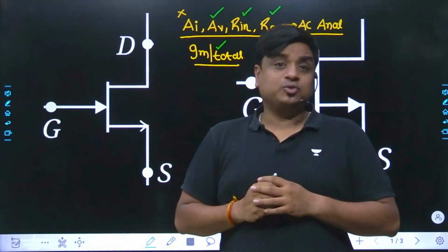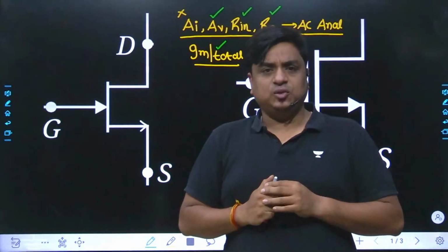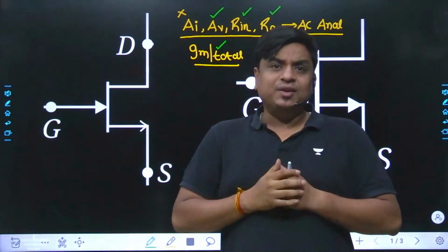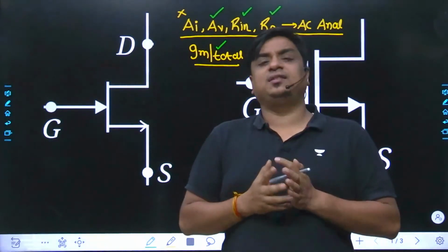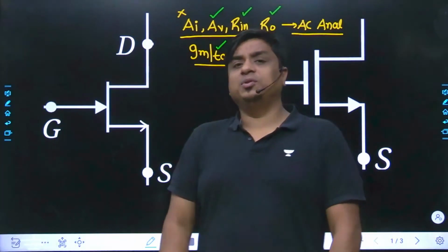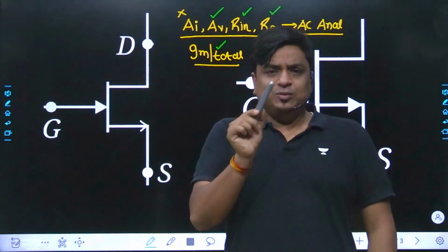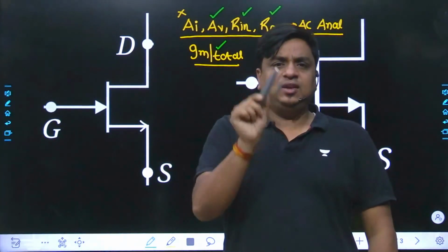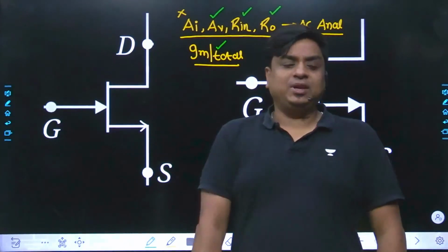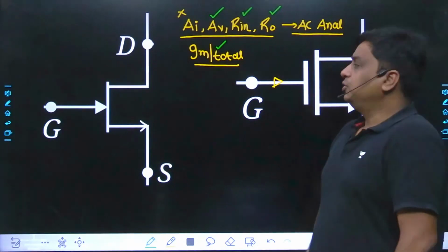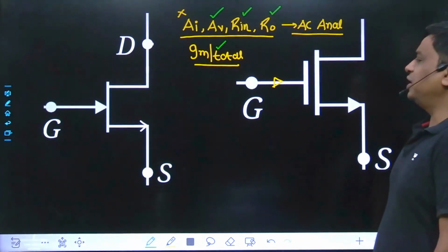As we know, the voltage source has the internal resistance as 0. So all of the voltage sources would be kept short circuited, and all of the current sources have their internal impedance as infinity. They would be kept open circuited. Same goes with the capacitor. Capacitor C is taken very large, and hence XC = 1/(2πFC) is kept at short circuit. So till this point, I don't find any of the students will have any kind of doubt now.